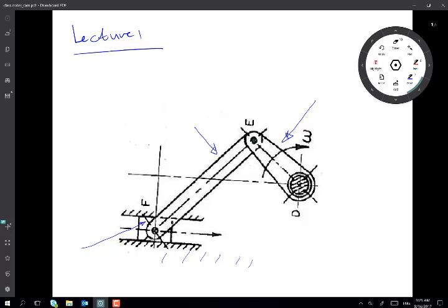Even with steel, if I give you a steel bar and a force applied on the bar axially, you should be able to calculate the deflection that occurs due to this force, based on the dimensions of the bar and Young's modulus. So there is always some deflection involved in the transmission of force.